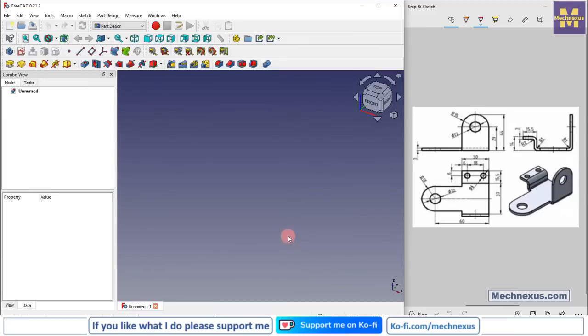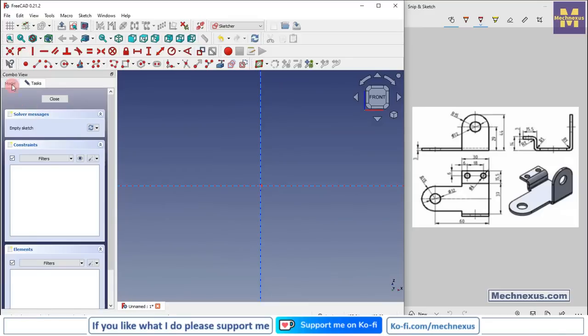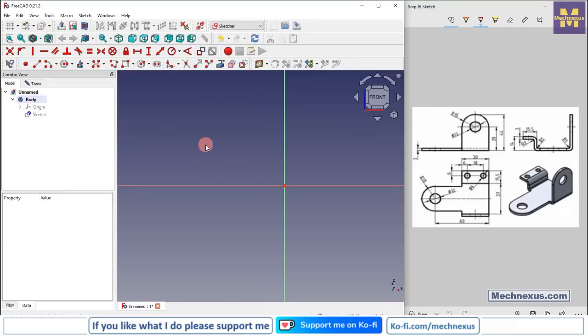So here I have created a new file, and I will insert my body, and I will turn on my origin plane, select the front plane and create a sketch. Now switch to the model tab and hide the origin planes, and now we will select the polyline tool and create a rough profile, and the profile is of the front shape. So here I have made this profile.